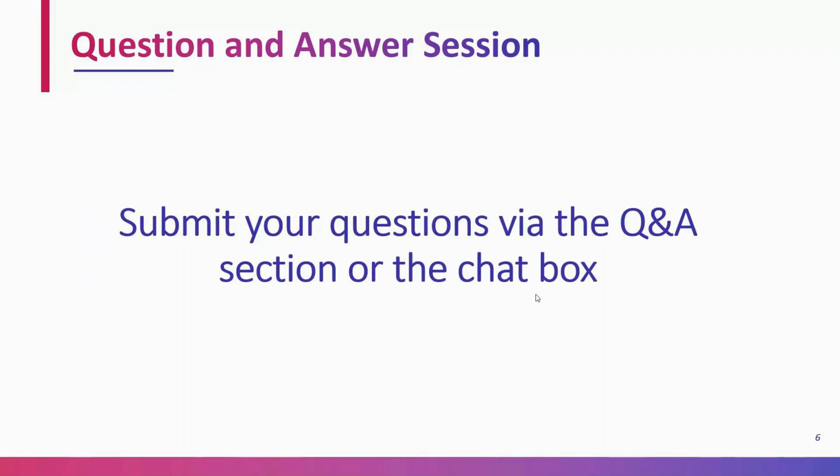What is the burnout temperature, Magesh? Generally, it's ash-free material, free of antimony. It can melt at less than 680 degrees Celsius, like wax. So you will get ash content of less than 0.05%. Let's move to the next question.